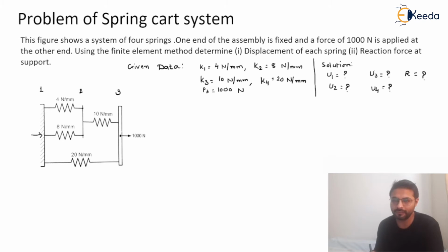The first step is to convert this problem into a free body diagram. Let me first show you how to convert. This is my fixed end. Here you can see there are three nodes, and in between there are elements.